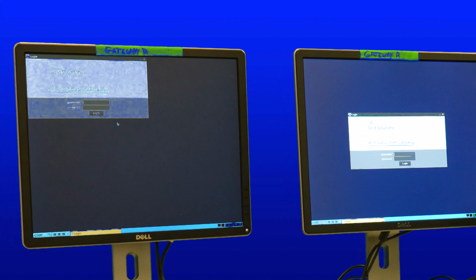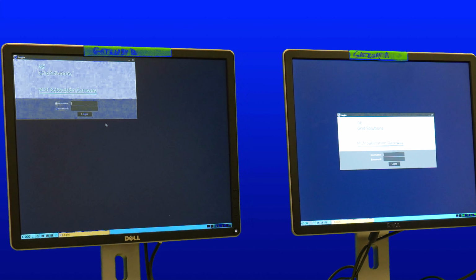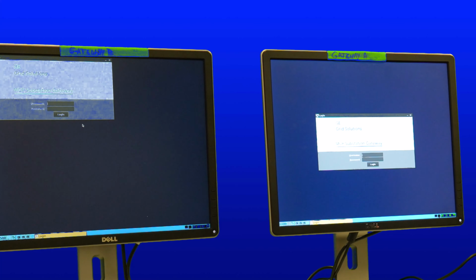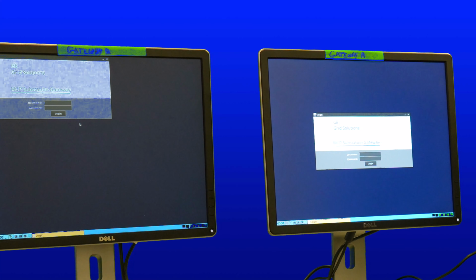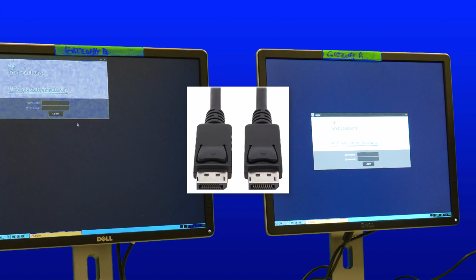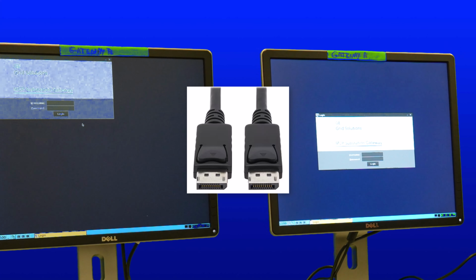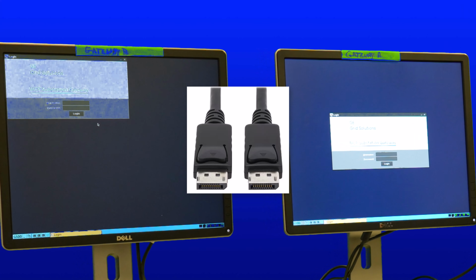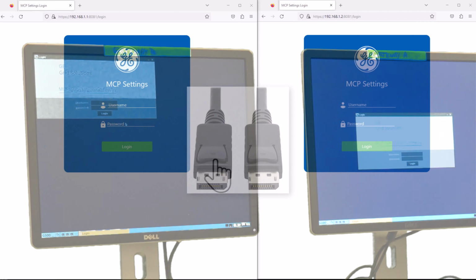Now, for the best monitor connection, make sure you have a DP connection cable, just like this one. It saves you from some non-compliance or non-conformity. If you keep changing to HDMI or DVI, it may not connect to the G500. So the best is a DP to DP connection.